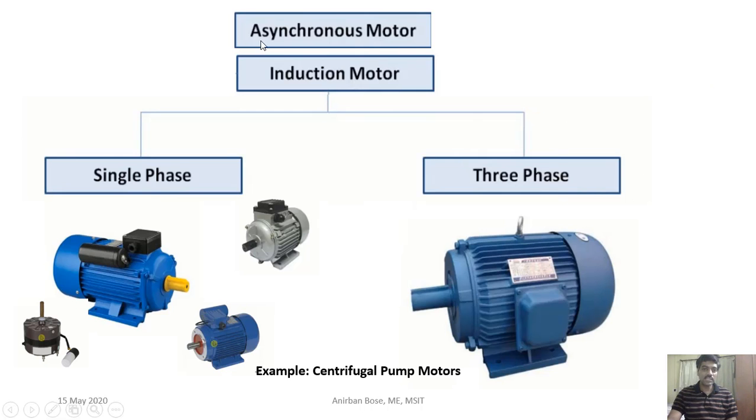Now come to the asynchronous motor. Asynchronous motors are also called induction motors. These can be of two kinds, single phase or three phase induction motors. Remember that a single phase induction motor is not self-starting, but a three phase induction motor is self-starting. So for starting a single phase induction motor, either resistors or capacitors are used.